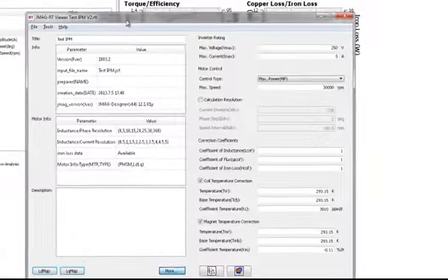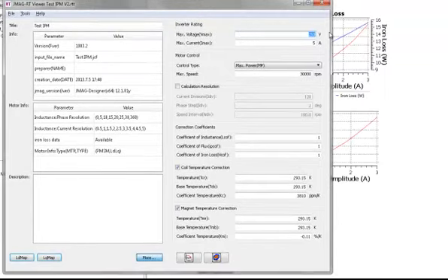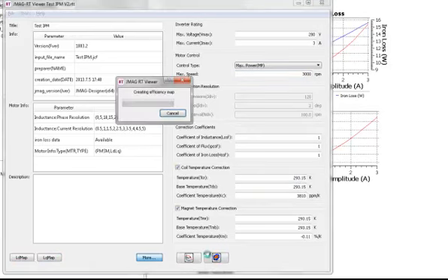So now if I go to more, let's set those same inverter properties up to 3000 RPM. And again, I won't change any of these correction coefficients. So inductance is 1, flux is 1, iron loss is 1. Temperature correction for the magnet and the coil, we'll leave at room temperature. And click on the inductance map feature. And what we should find is that the data should be fairly similar. We're operating in a very nice rated range. We're not going into heavy saturation. So the performance should be fairly similar.